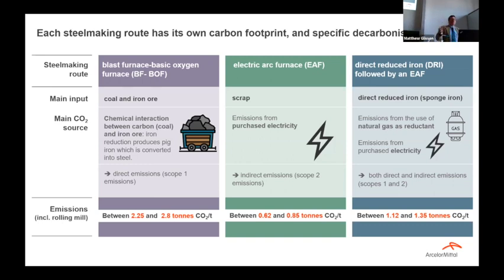very thin profiles. And for those who know a little bit about steelmaking, this is not possible with recycled steel. You cannot roll it as an EAF recycled steel. You cannot roll to 0.2 millimeters. There you still need iron ore. And we will stop the blast furnace route in some years. And we will then use iron ore that has been already treated, not with natural gas, but with oxygen. And we will melt that down in an electric arc furnace. And by doing this, we can achieve this very, very low CO2 emission level.